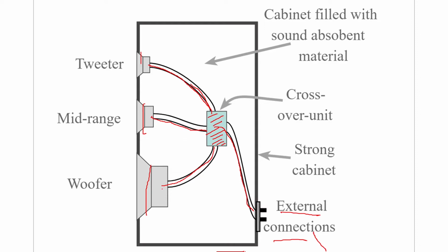same. You will be having a voice coil placed in the magnetic field, and the voice coil will be given the electrical signal. When the electrical signal reaches the voice coil, it will form its own electromagnet. That magnetic field, when it interacts with the permanent magnet, will align itself or start vibrating. That vibration is connected to a diaphragm. The diaphragm will vibrate, and sound waves are generated. So this basic principle will be more or less the same in tweeter, mid-range, and woofer type of speakers.